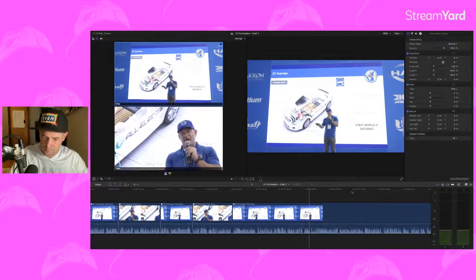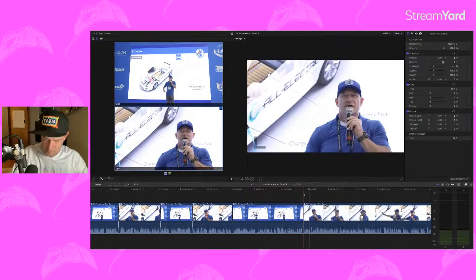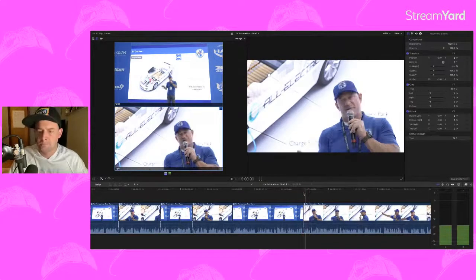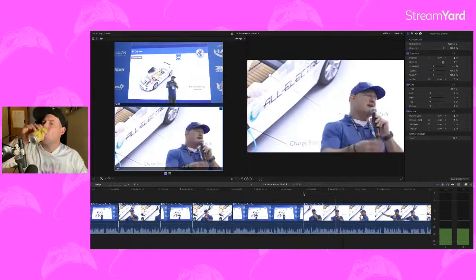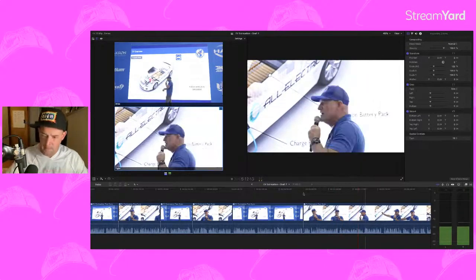So the days of being able to engage the vehicle and cut the 12 volt power every time, all the time, are fading. You've got to think twice about that now on EVs. You understand how that's going to affect your operating sequence and whether or not it's a move that you want to make or don't want to make.